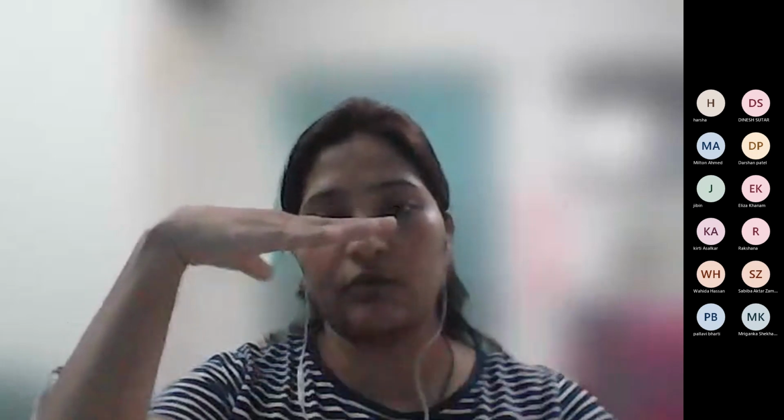But in case of plume rise, if the inversion condition is below the height of the stack, now what happens? For example, this is your stack, and below this we have an inversion condition. So whatever pollutants are dispersing from here will tend to disperse above this layer. So what will happen is that below this, down to the surface of the ground, the pollutants will be minimum in this region. So in this condition, inversion is good for us. So it is a condition-based thing, depending on the situation in which we observe the inversion.